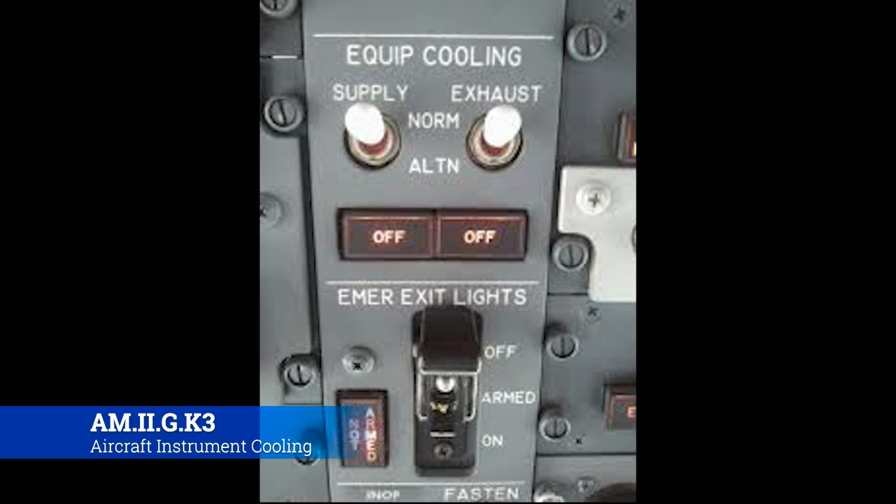There are two fans that can work in the normal and alternating mode, and I will tell you they are very loud. If you're up in the E-bay, you might as well just wear some earplugs or at least a headset with radio capability, so that way you can talk to other people, because it's going to scream at you. It's super duper loud. And what that's doing is it's moving air through the E-bay and through the channels on the ear racks.